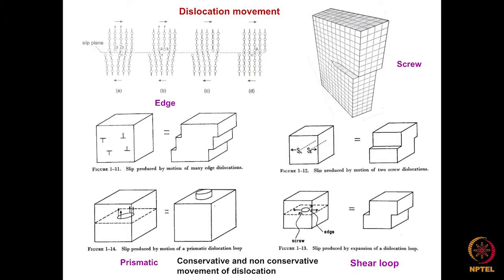So dislocations are generated, they come out of the sample surface, and generate some shape change to the sample. If the dislocations don't come out of the sample surface, no shape change will occur. But when they move inside the sample, the stresses and strains at different regions will change within that sample. That's what will happen. This we will talk about later.